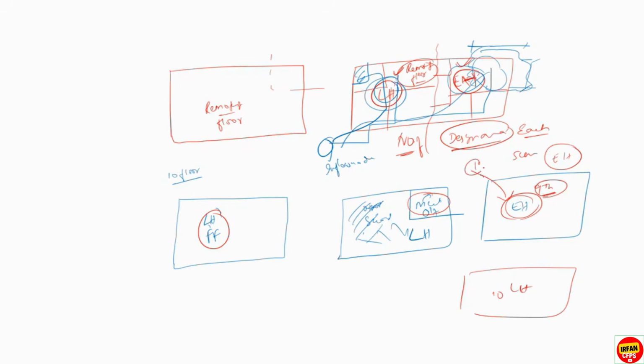So one scenario will consider extra hazard, and one scenario will consider the remotest floor and remotest area of light hazard. If you have different hazards, you have to consider each scenario and perform the calculations.